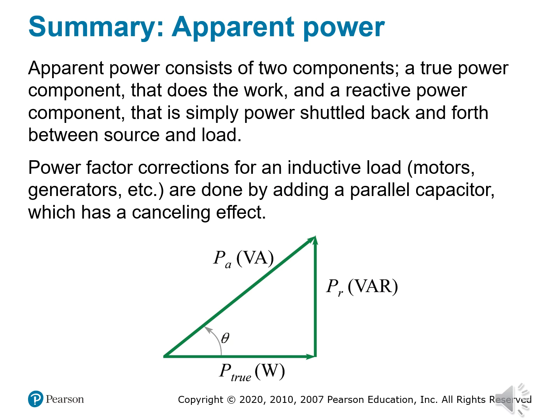Capacitors produce leading VARs, which cancel out the lagging VARs from inductive loads like motors and coils. The result is reduced total current, lower apparent power, higher power factor, and greater efficiency. Apparent power is the total package your system carries, the real plus the reactive. It's good to understand this so you can minimize it, and it happens to be one of the most cost-saving things you can do in industrial power management.